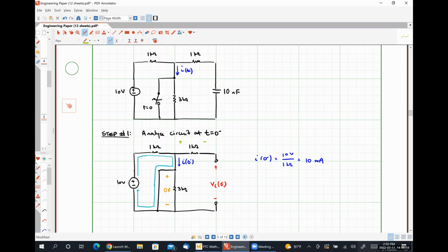All right. So back to my prior question, what is the voltage drop over the 1 kilo ohm resistor with the polarities that I've indicated in green? So what's the current through the 1 kilo ohm resistor on the right? 0. So since the current flowing through the 1 kilo ohm resistor is 0, the voltage drop across the 1 kilo ohm resistor must also be 0.